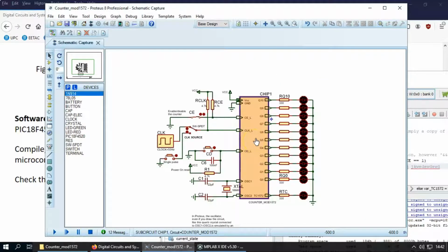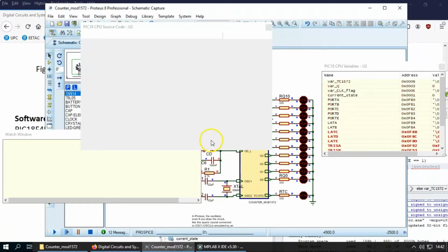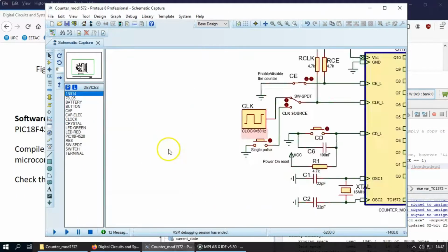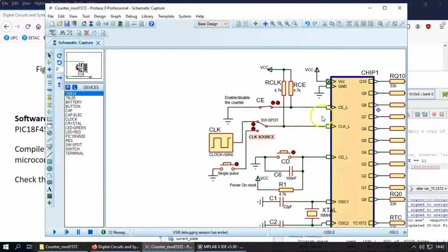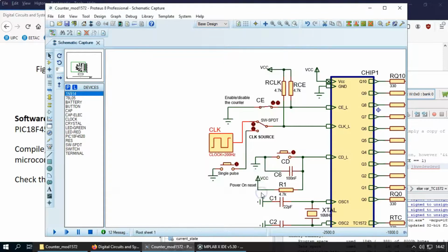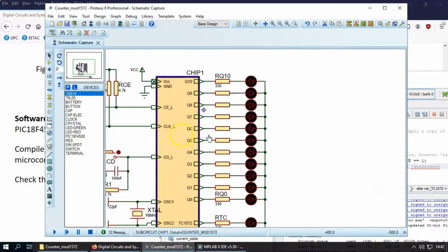Don't forget, before finishing the demonstration, to check that everything goes fine. For example, if I plan a 200 Hz clock, let's see if this is right. Every 5 milliseconds I will have an interrupt. This means that every 5 milliseconds I will get an interrupt signal. How can I check that, guys?